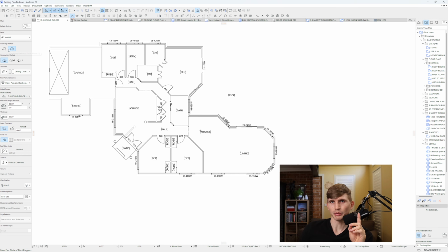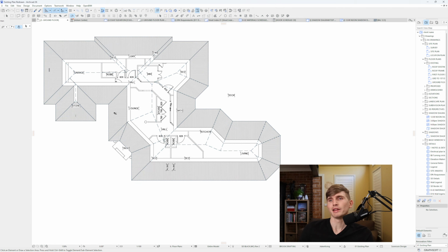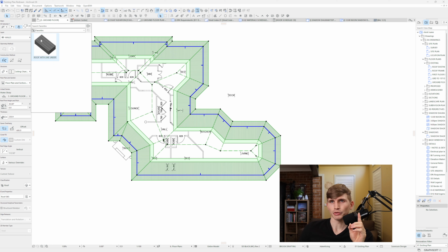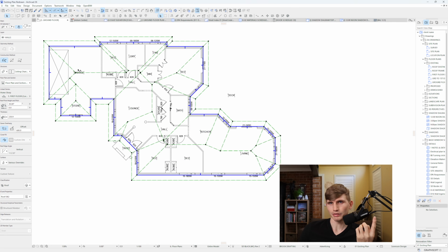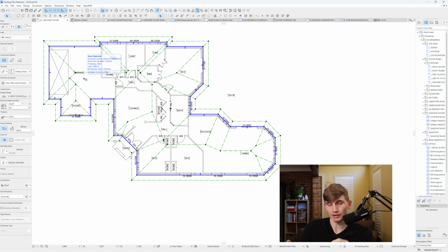This one just here, and we'll make sure that it's set to geometry method multiplane. Now what we could do is just hover our mouse over the exterior wall and click once. That's going to create our roof. It's relatively close, but there's a few things that we'll need to tweak. So I'm just going to adjust this one so that it's set to our parameters where we've got the roof line shown, but not the rest of the actual roof. I'll make a dedicated video on this because there are a few steps to it.